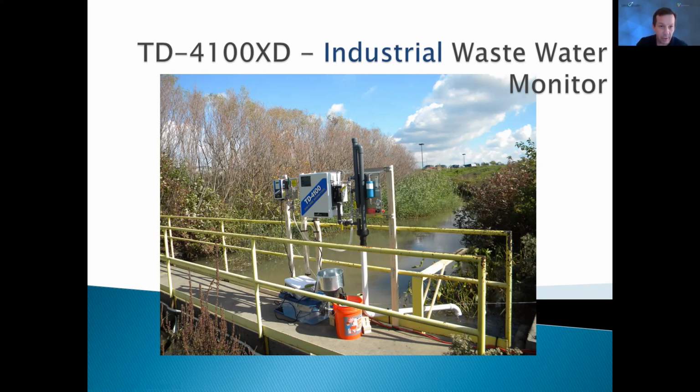Over here, there's a little industrial plant. Back here, there's a parking lot. This river is actually the industrial outfall of the plant, flowing into a major river just off to the left-hand side here. This little walkway that you're seeing is actually a weir. The water goes underneath that, trapping all the oil and other things that float upstream of it. Then there's a lagoon and finally outfall to the river.